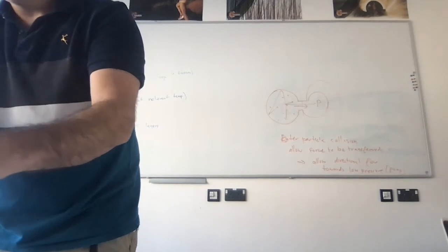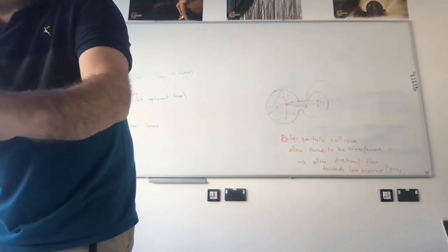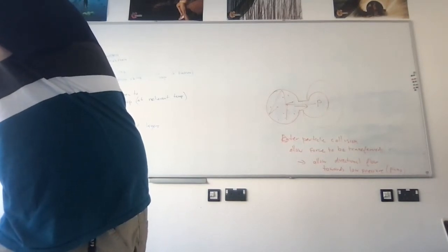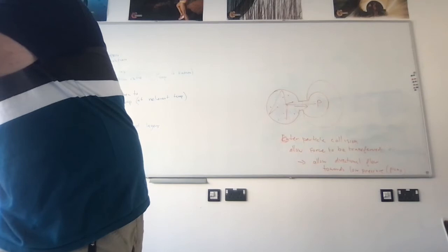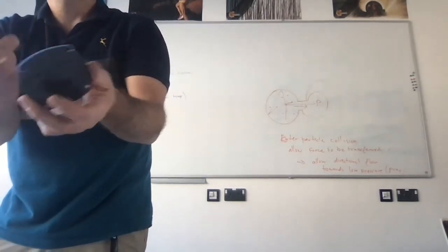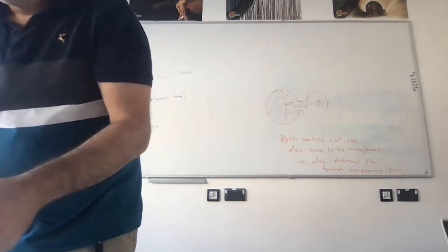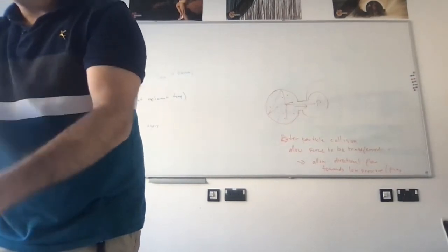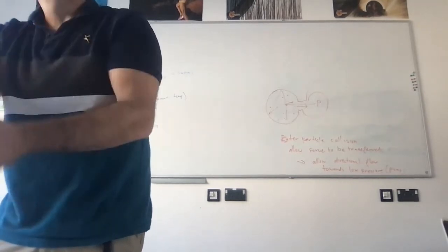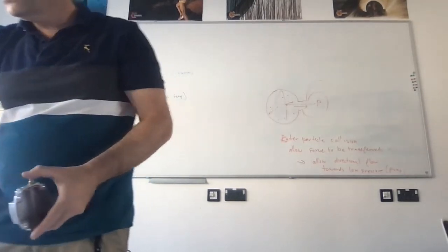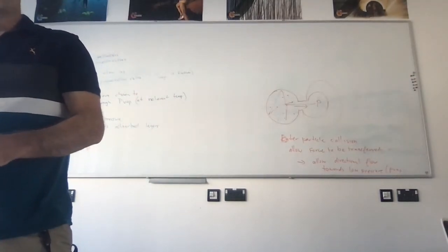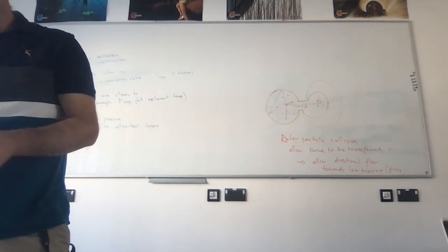You see this rubber here? When the gas is pushed outwards, it can do what my finger is doing now. When the gas wants to go this way, the difference in pressure seals it. So these are like one directional valves. They go to two different chambers, and each time gas is pushed out, gas pulled in, pushed out, pulled in. It's kind of the equivalent of what we try to do with this syringe. So this would be a piston pump.